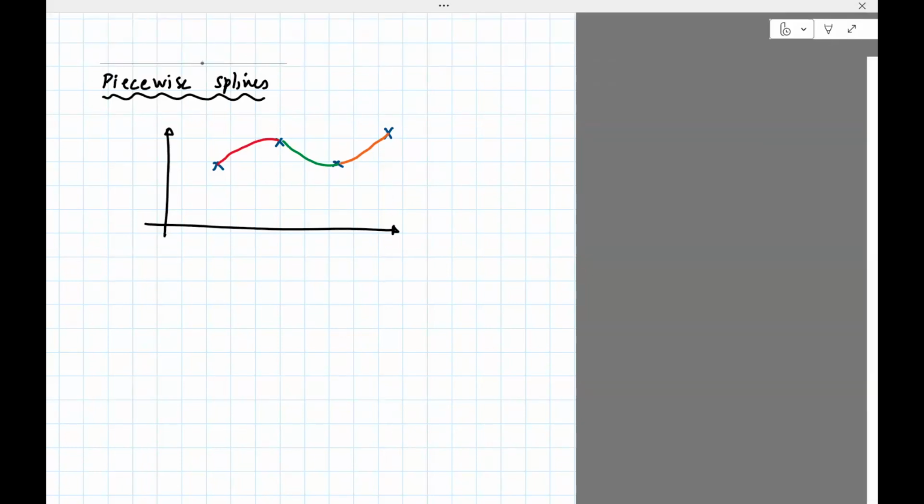So let's call that, say, Q1, Q2, Q3. So Q1, Q2, Q3 are third order polynomials. So why use third order? Now, most times you want that curve to pass through 2 points, right? The start and end. You also want to ensure some kind of continuity where it passes.